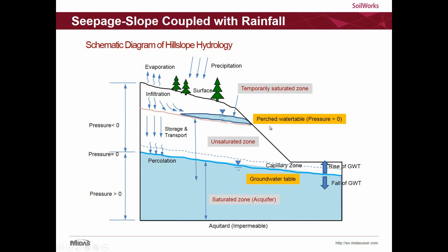destabilizing the slope. If the engineer does not perform seepage analysis, the terrain is assumed to be completely saturated upon precipitation due to rains for slope stability analysis. However, if the condition exists like this one, as shown here, then assuming the fully saturated soil is incorrect. The engineer has to perform seepage analysis to get the actual pore water pressure for slope stability calculations.